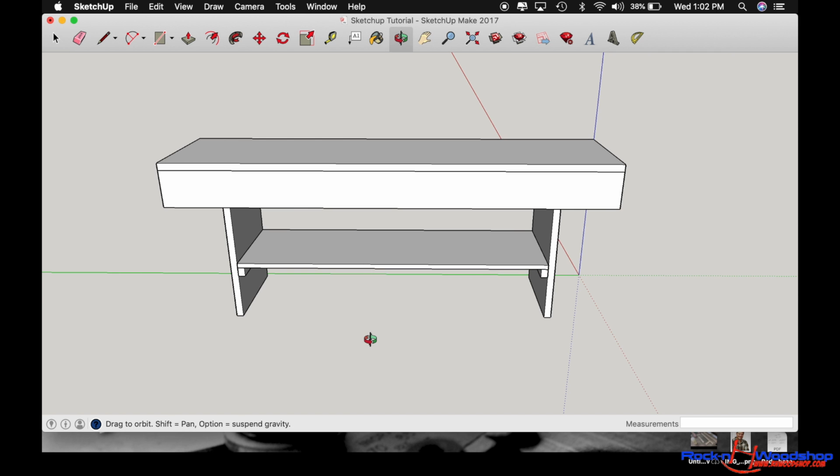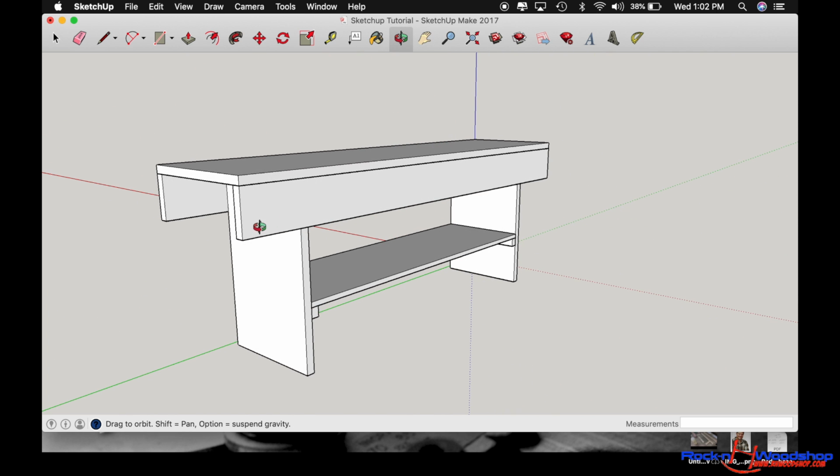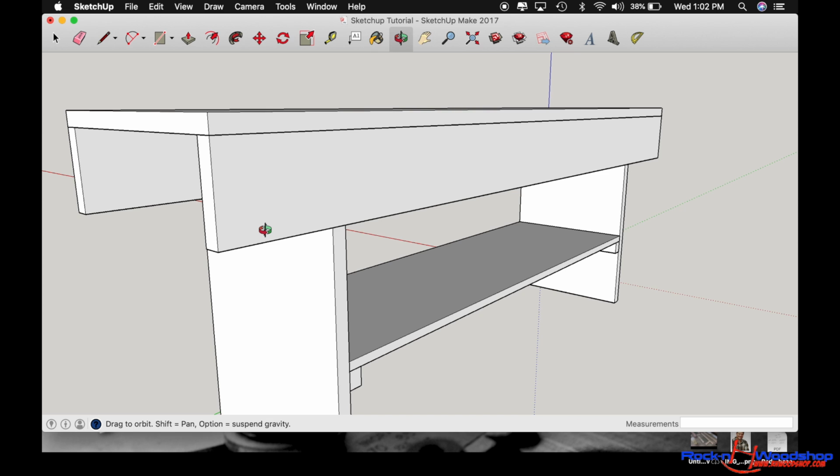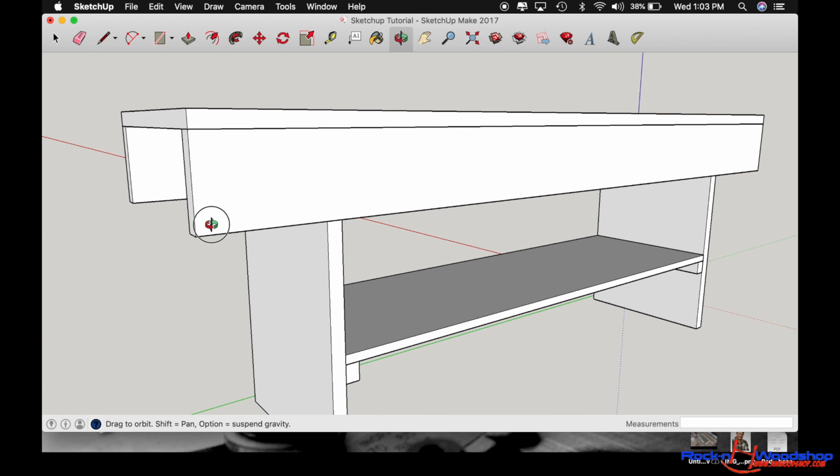Okay? So aprons right here, you can see they have a really sharp point, and if people walk by that, they're going to get hurt because it may grab their shin. So let's make a chamfer, a 45-degree chamfer that starts at this corner and goes over 45 degrees and cuts that part away.